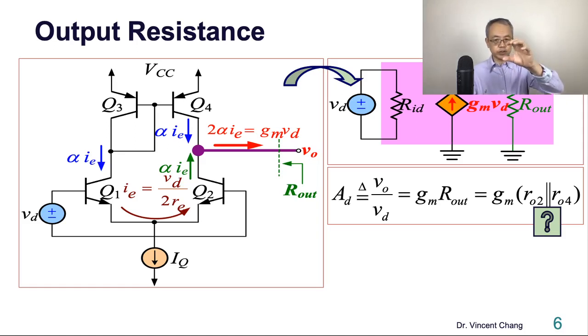The voltage controlled current source: if VBE is not 0 in AC, okay? Not DC, we are doing the AC analysis. Don't get confused between DC and AC. So VBE2 is not 0. Then you have to consider the voltage controlled current source inside the transistor. So there are 2 components working: GM VBE2 in parallel with R2. So how can you say that when you're looking down it's just R2?